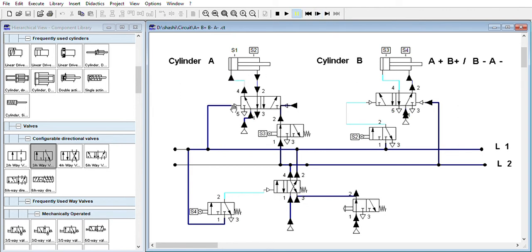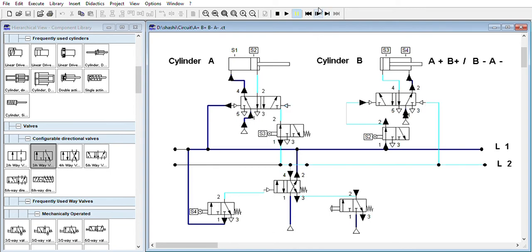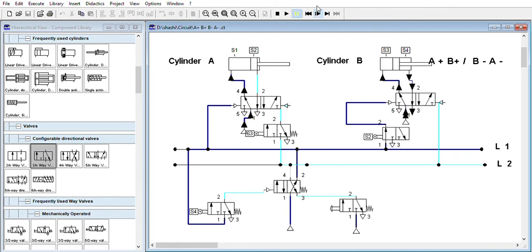Sorry. So here you can see your L1. It will need A plus operation to reach S2 first. Once it reaches S2, this will actuate this one. So here you can see L1 is only live, only one. Now this will actuate, and this will lead to B plus. So this is simple till B plus.